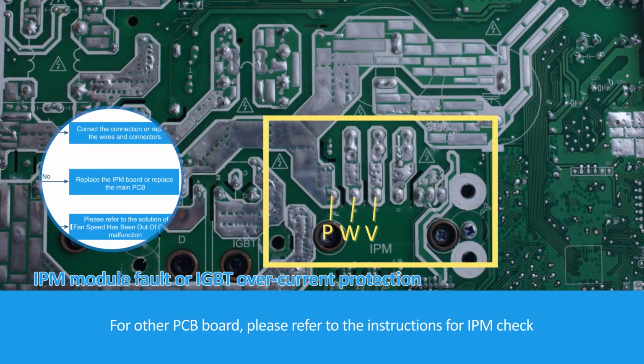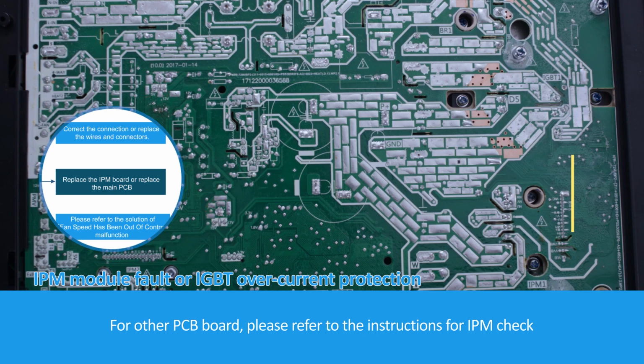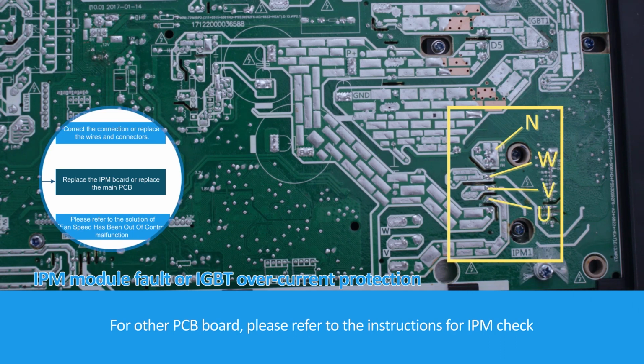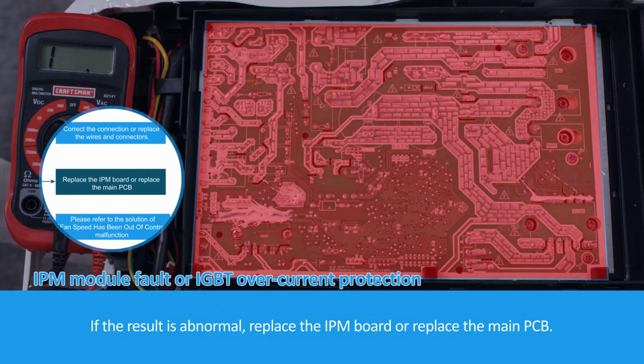For other PCB boards, please refer to the instructions for IPM check. If the result is abnormal, replace the IPM board or replace the main PCB.